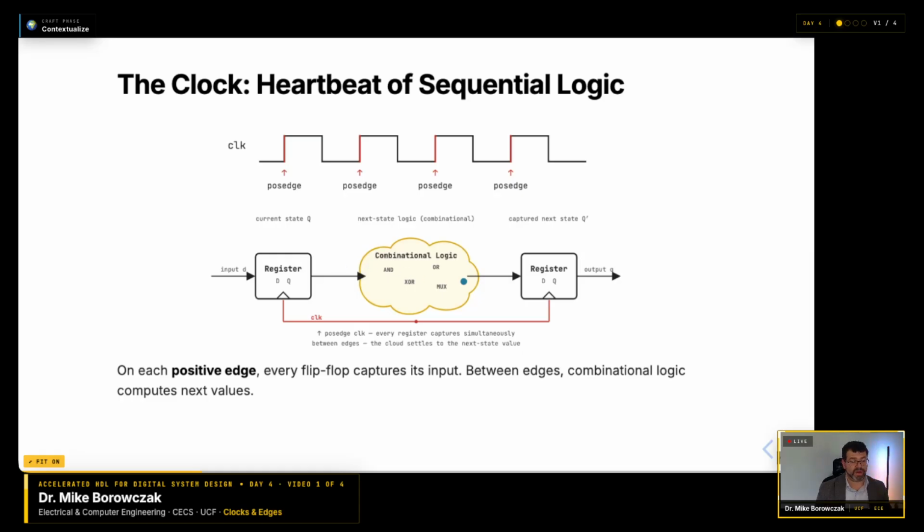What happens after that positive edge? So that's the whole top edge of the clock, then the transition down, and that whole bottom edge of the clock. We're doing all the combinational logic that we can. We're basically fitting as much as we possibly can in there. And then basically the process continues. So we do all that combinational logic work. That becomes an output from that combinational blob there. And that becomes the input that will get snapshotted again at the next positive edge of the clock. This repeats over and over again, at the rate of the clock.